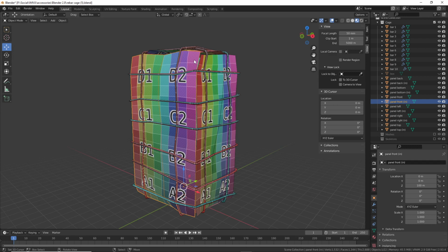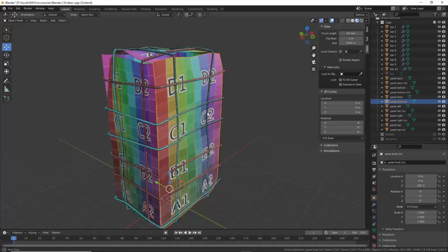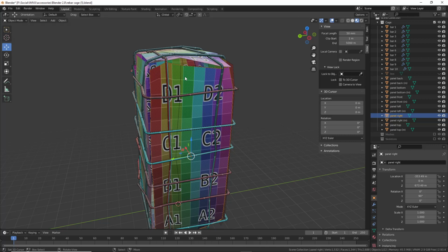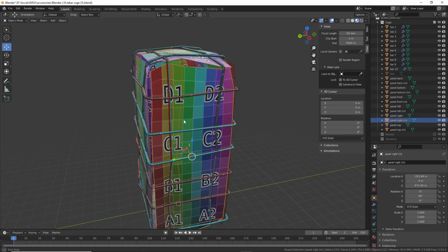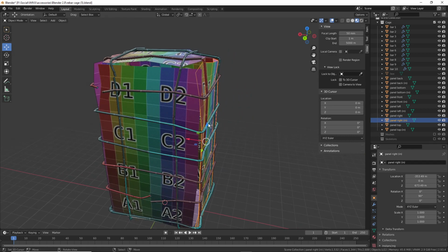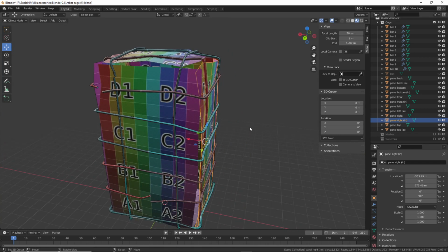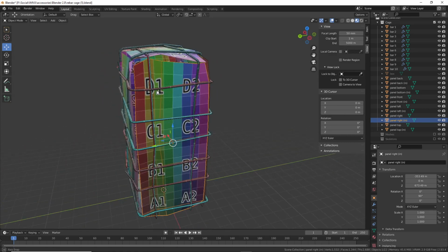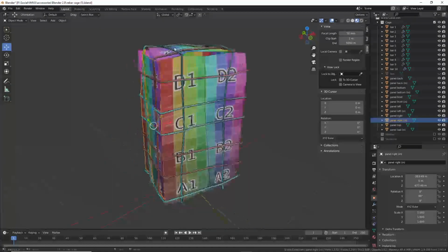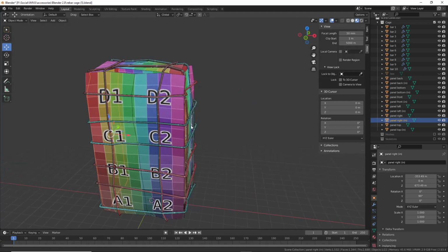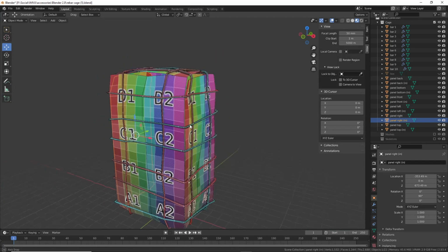It doesn't affect Shininess so much but it does with normal maps. So what we've done is basically duplicated these panels so that we've got separate meshes on the inside and the outside of the object, because we need to make sure that the normal maps on the inside of the mesh react properly with respect to scene lighting.